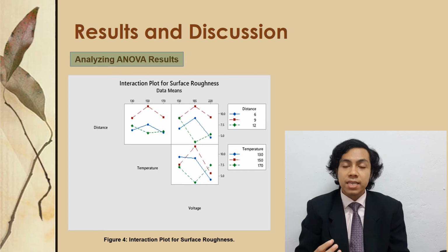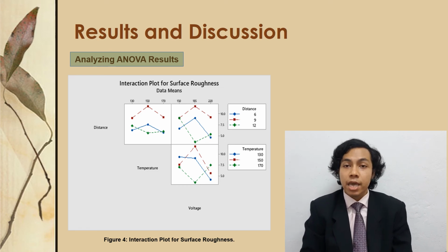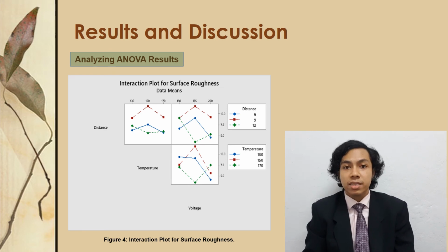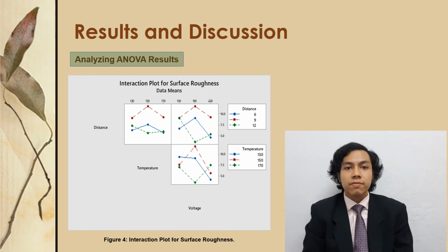This narrows down the findings by highlighting that the heating distance is the most significant factor in forming the concave shape of 5 mm ABS plastic plate using the self-developed vacuum forming machine, as compared to the heating temperature. However, the heating temperature factor also needs special attention as it does contribute to the overall vacuum forming process performance.